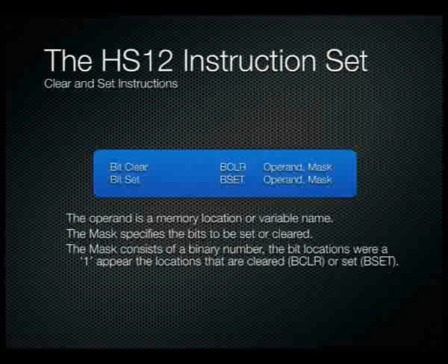It is the command, in this case bit clear or bit set, that defines the action we want to do with those bits. So the mask defines the bits we want to change, and the command defines how we're going to change them. You've got to keep that very clear in your mind when using bit set and bit clear. They're a great command to use. They make your life a lot easier, but you've got to know how to use them properly.